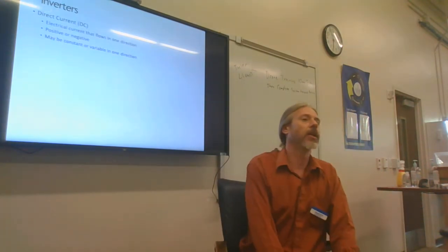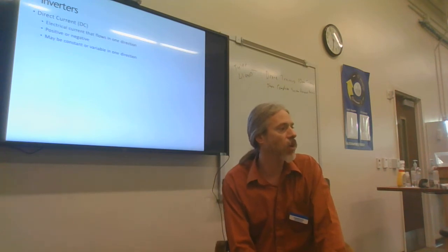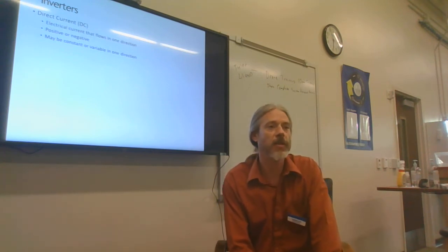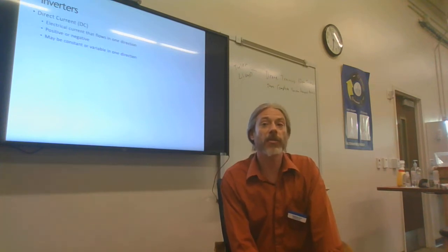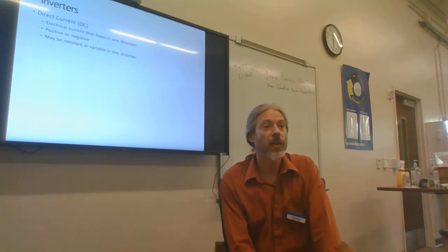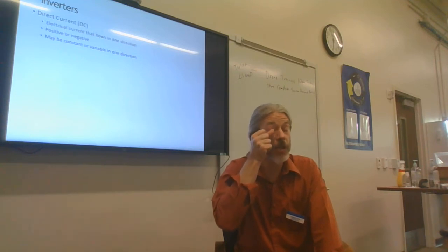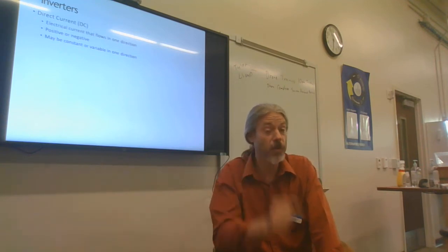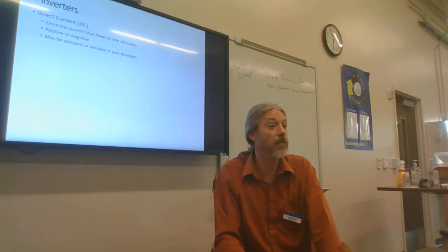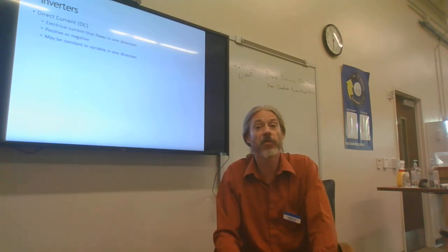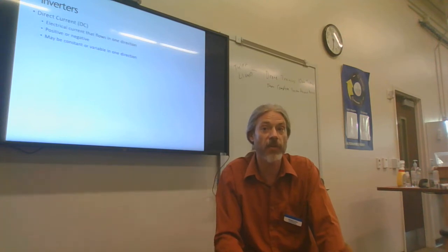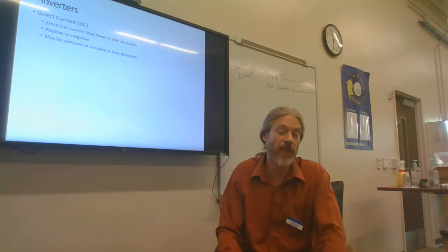The terms line commutated or load commutated will be discussed after a while. But there are smart inverters that can do both. They can be both line commutated and load commutated. Those bimodal or multimodal inverters are capable of exporting additional power that is not needed back into the electrical grid and capable of running emergency loads or backup loads in the event of grid failure.